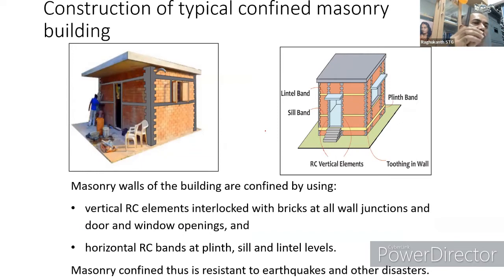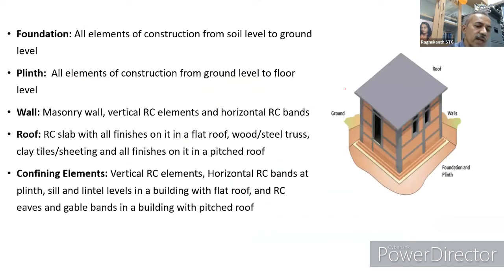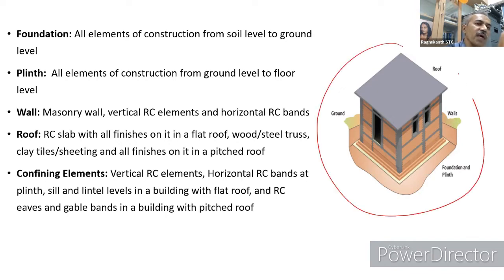They also wanted, and we have also provided, guidance on how to construct new buildings, simple masonry based, because they don't want to go for RCC, only cheap available materials. We have given pictorial details, like the lintel band, sill band, foundation, and plinth. Most of these structures are constructed by local masons, so that person also should be able to understand. So we have given these graphical, nice interpretations.